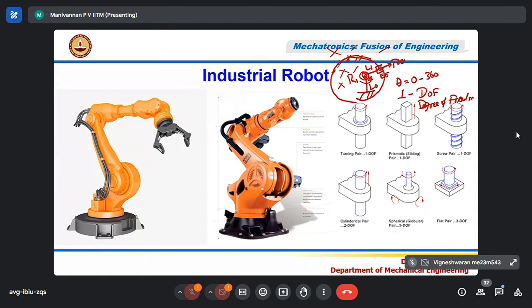For example, similarly, I showed you previously one prismatic joint. I have the L0 link connected by a prismatic joint, which is nothing but a piston moving inside the cylinder. The whole thing is the joint. I call it P1, this is my L1, and the end effector is there. If I attach a tool, this can extend. The piston is here, at the end, which is the end effector position. When the piston is moved to the other dead end, the right-hand dead end, the end effector will be here.